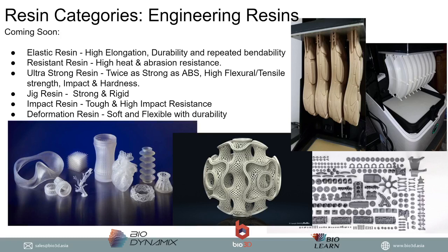So elastic resin will have a high resolution and low shrinkage after post-curing. So what you've designed is what you'll get. It has a lot of elongation give. It's got 120% of printed length, which means if you printed a bar, let's say that's 10 centimeters long, it can stretch all the way to a total length of 22 centimeters. That's a lot of elongation within the resin properties.